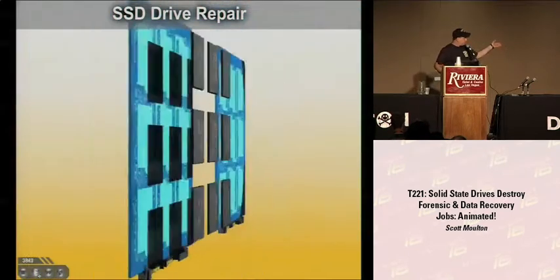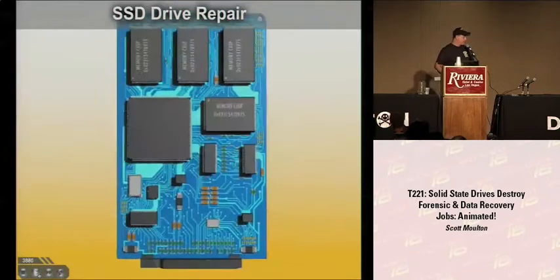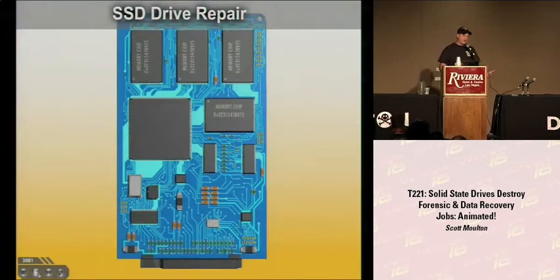Then you also have this number of chips that you would basically have to unsolder and resolder. So now it becomes infinitely more complicated than it was before. Getting one or two chips, maybe you can get those right, but it's pretty easy to mess up if you got 20 to do or 15 or something like that. And there's one other complication, which is you still need a donor drive. You still need one that is exactly the same one as the one you have, because you're going to rip it apart so that you can take all these chips and move it to it so you can repair whatever's broken piece by piece. So we've now become less of a mechanic trying to fix a mechanical problem and more of an electrical engineer, having to have some other skills that we didn't have before.